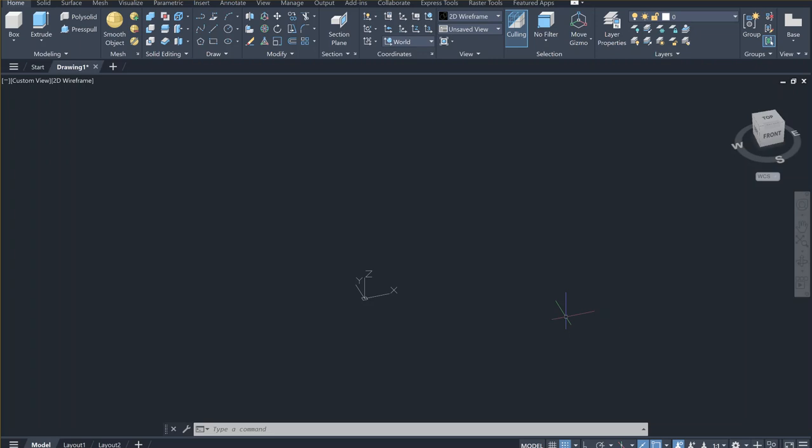All right, so let's move on and create a 6-inch line. Because it's 3D space, I want this to be a 3D polyline. I can type 3D poly and get it over with. But I want you to find out also where the 3D polyline is on the screen, on the menu, on the ribbon. Right here. Click here. Now the computer is prompting you.